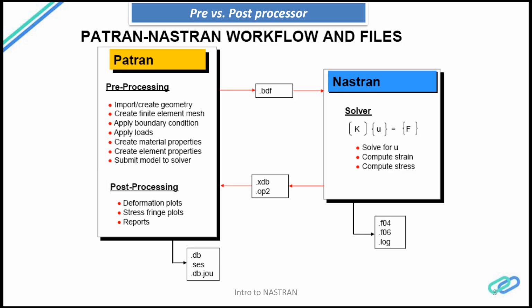So to give you a very quick recap, once the finite element model has been created, Patran will generate a type of file called a BDF file, in which the entire model will be written down in a statement format.